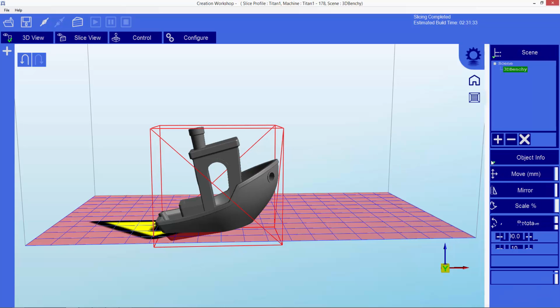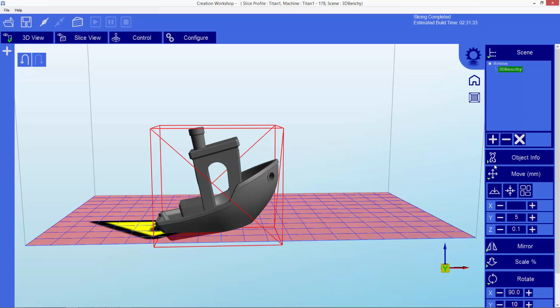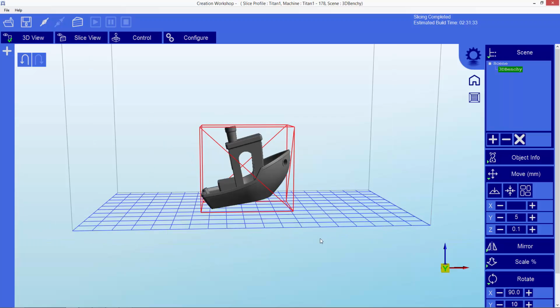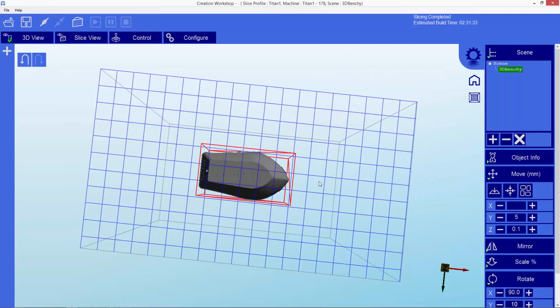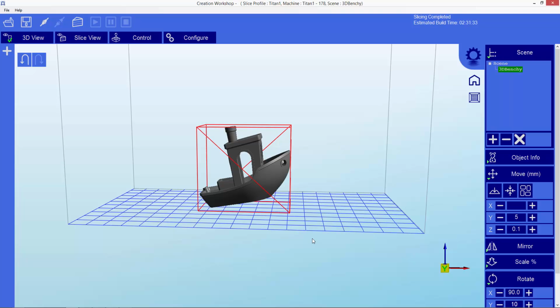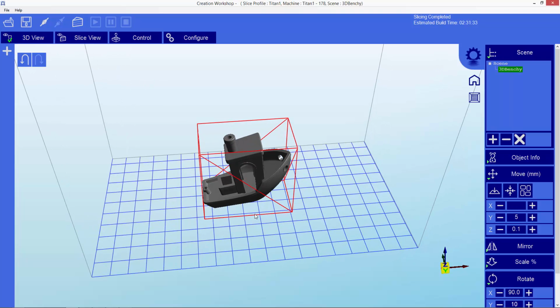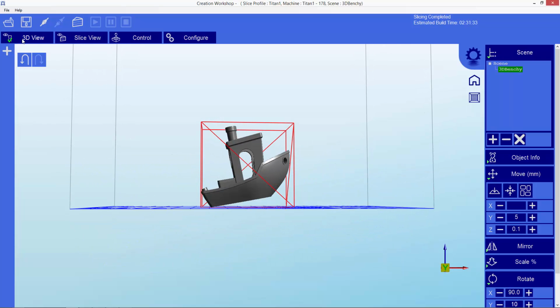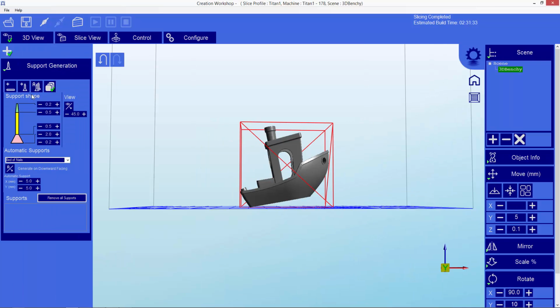And then I'm going to need to move it back here, right? This would significantly change the cross-sectional surface areas now that I've rotated this by 10 degrees. But once having done this, I'm going to need support because now only this little edge is touching the bottom. And that means in order to get this to work, I would have to generate supports.